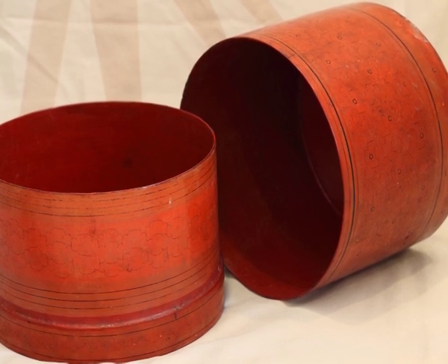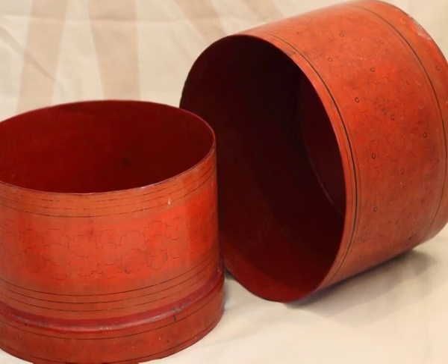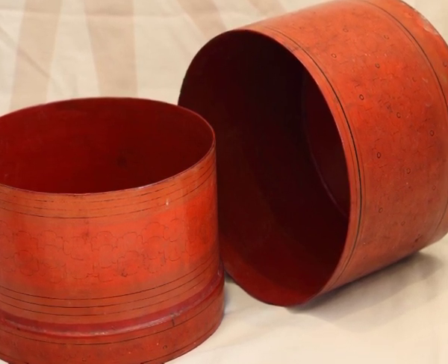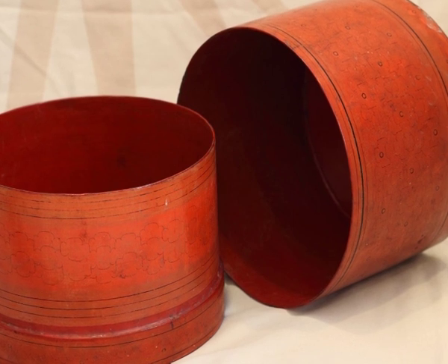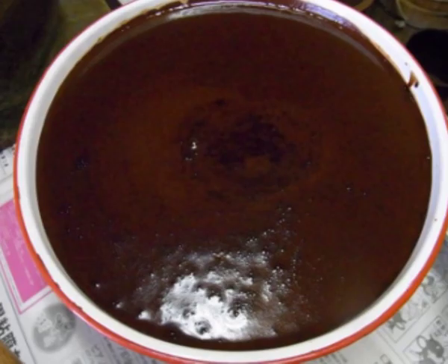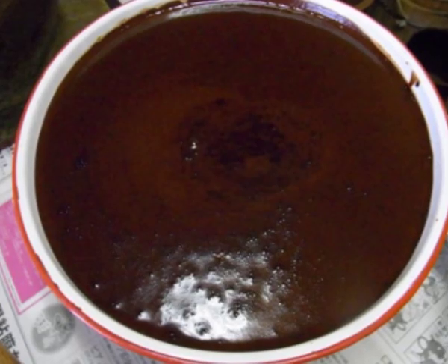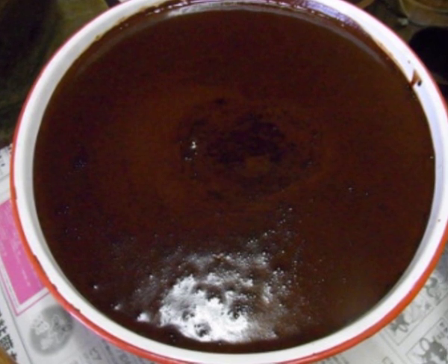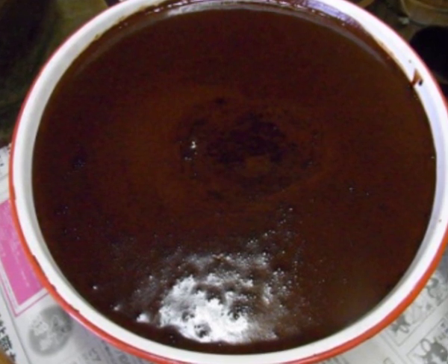The lacquer itself becomes the least important factor governing the success or failure of a protective system. It is rare when examining lacquer failures to find that the lacquer itself is at fault, and it is equally rare to find a lacquer that has failed because it has been chemically attacked. Properties. The first point to be realized is that all protective lacquer films are permeable and transmit oxygen and water.